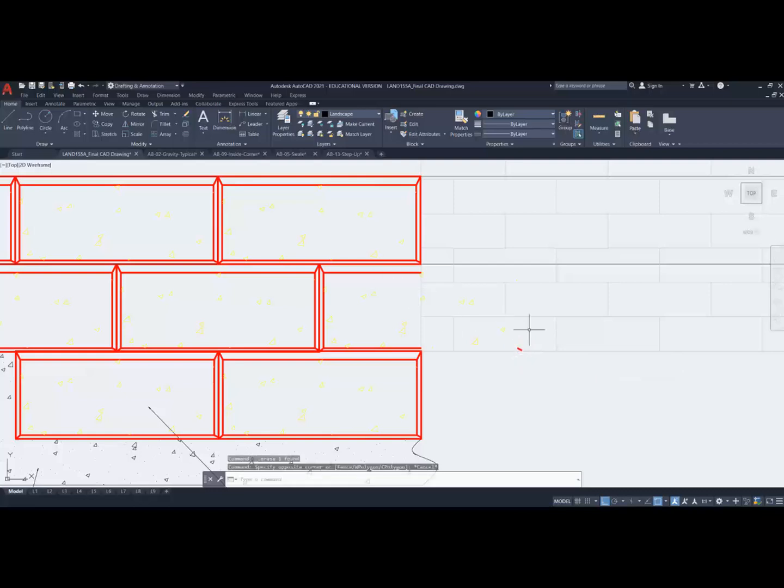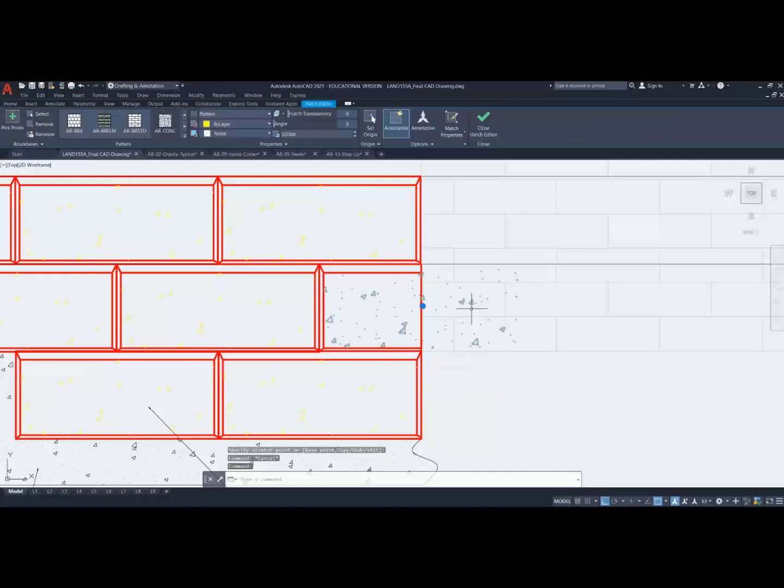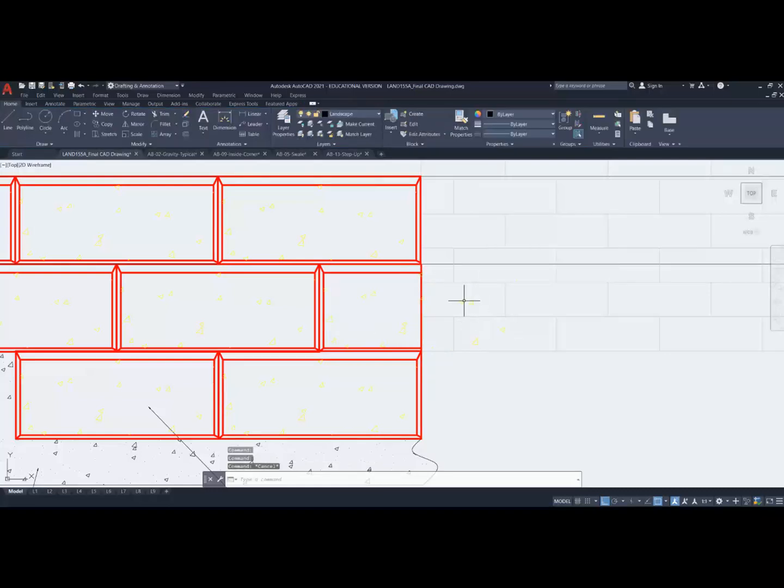Now, notice how it's missing some lines. I'm just going to use one of their existing lines and click it and move its position. So without drawing a line, I just used it. Now, I didn't trim the actual boundary of that hatch. So I got a couple of options here.